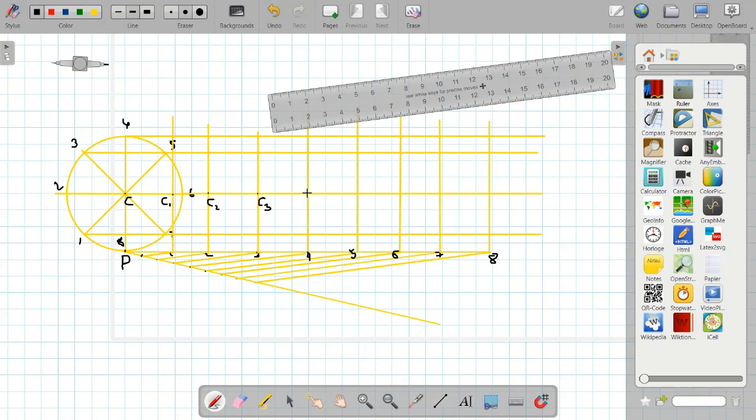and so on. Note that dimensions and these namings should be given in medium dark lines. The yellow ones are the lightest possible lines. This numbering will be in the medium part, and the involute or the cycloid which we will draw will be the darkest.